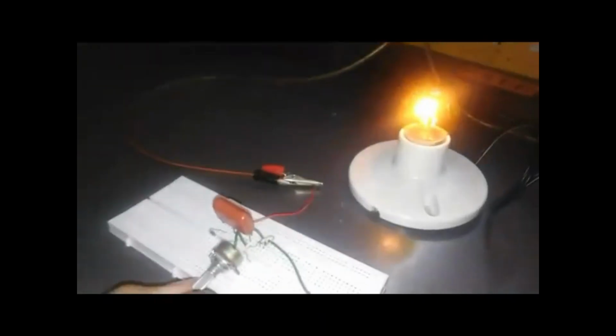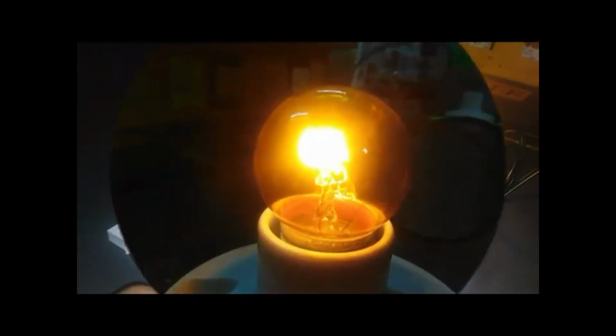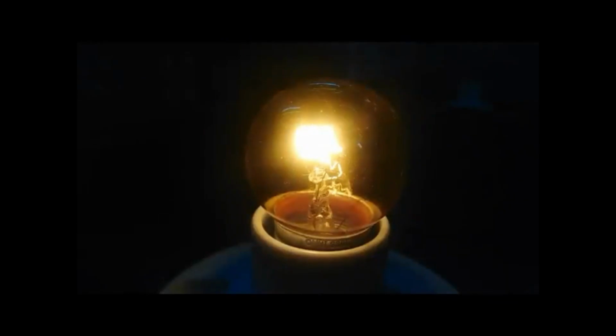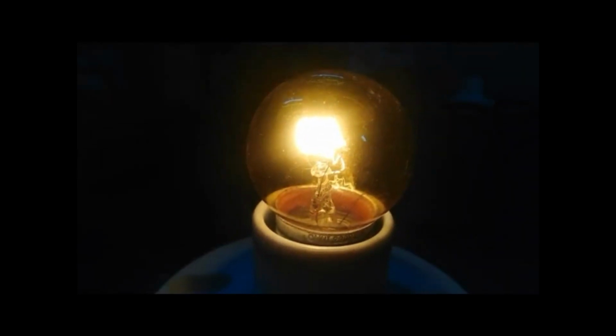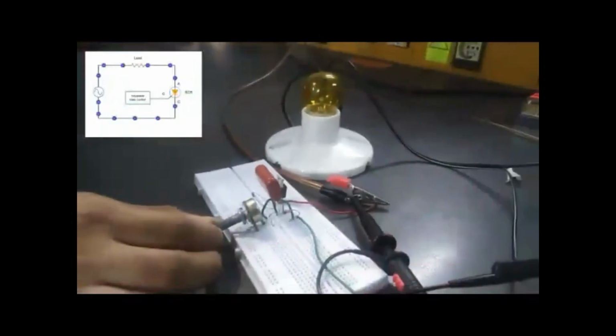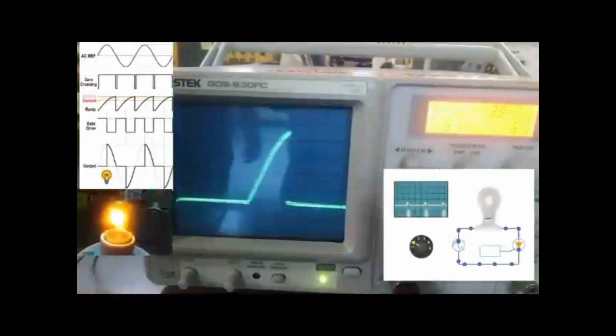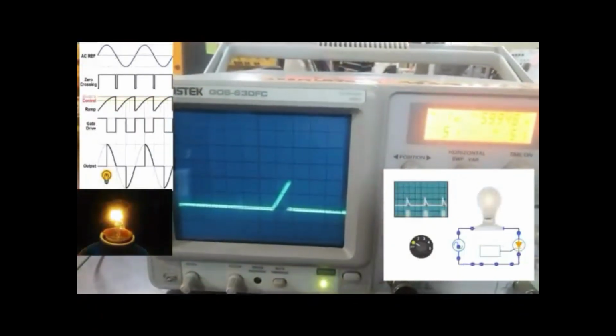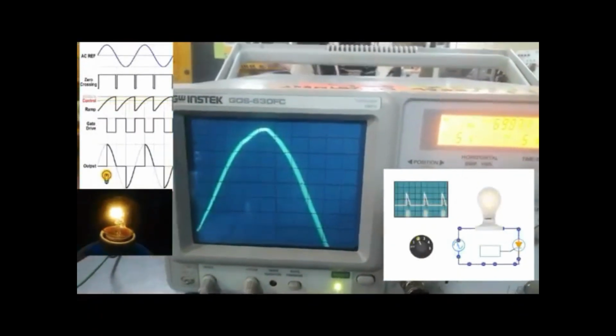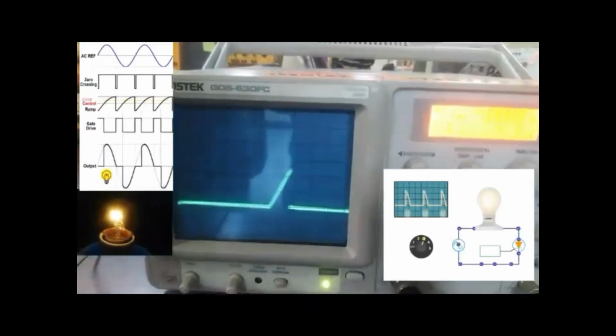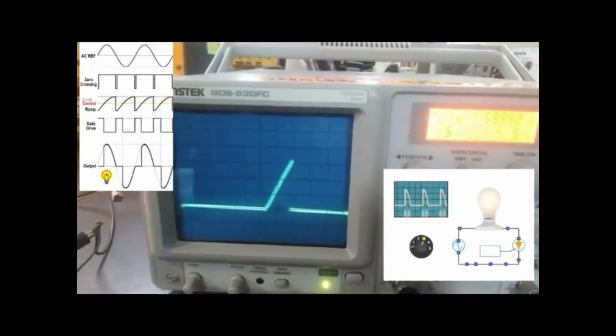Triac is commonly used in places where AC power has to be controlled. For example, it is used in speed regulators, AC bulb dimmers, and more. The common application of SCR is the light bulb dimmer. It's the switch of gate control adjusted to control the power of alternating current. Note the timing of the gate pulse and the subsequent change in the waveforms. Also, the average current flow increases, and the light bulb becomes brighter.